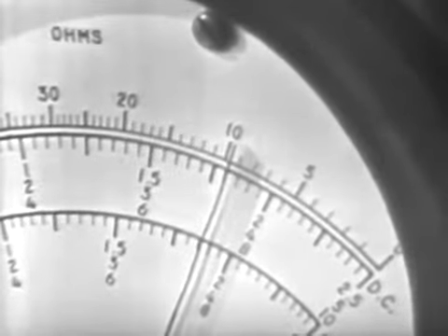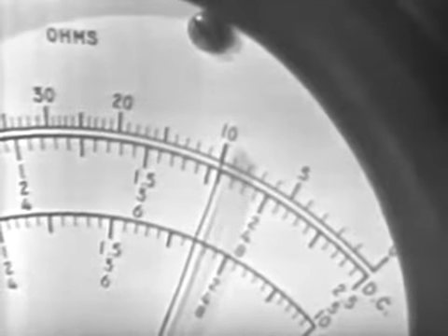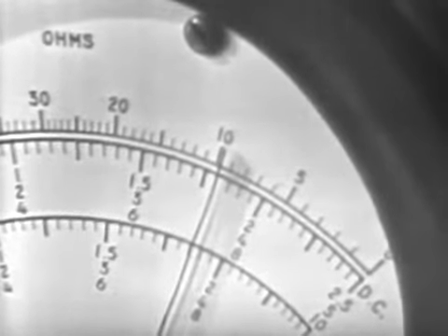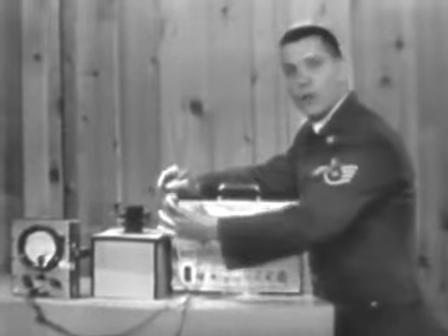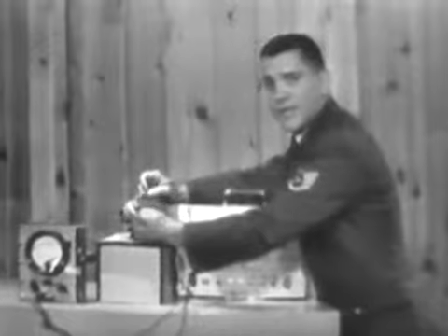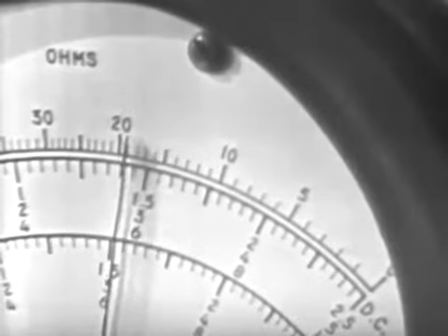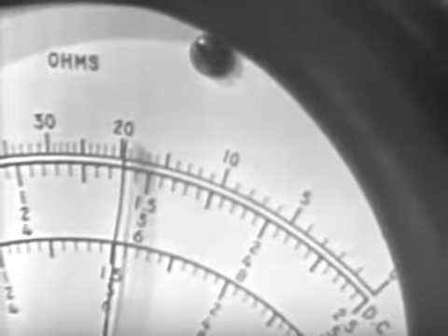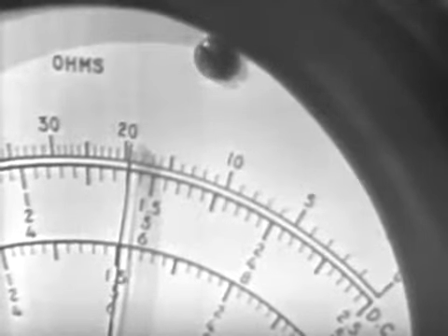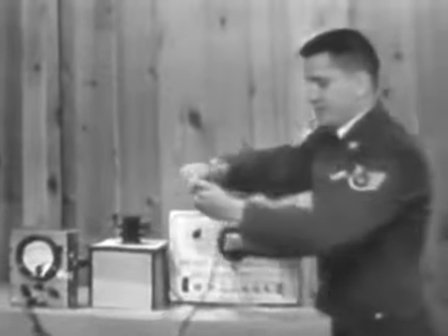All right, if we'll take a look at the meter now, we'll see that the primary winding has about 10 ohms of resistance. All right, let's go on over to the secondary winding and see how much resistance it has. Remember now, we're on the ohms times 1 scale, and this time we can see the PSM6 indicates about 20 ohms of resistance for the secondary. Now this indicates then that there's twice as many turns in the secondary as there is in the primary. So the turns ratio is 1 to 2, thus the transformer is indeed a step-up transformer.